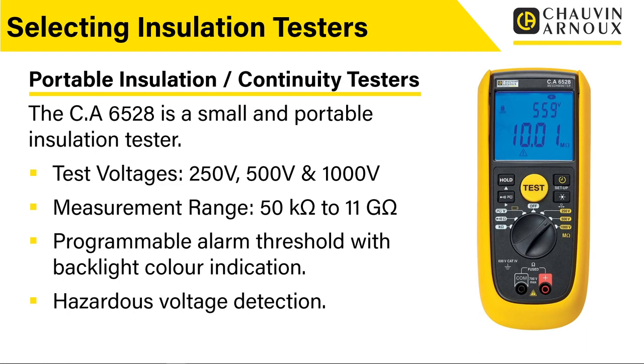So it's got a really wide measurement range there, and that means we've got a good range of values on this. It's got a programmable alarm threshold with backlight colour indication, so you can actually set at what resistance value you want the backlight to change red and tell you that it's failed or that it's lower than you would expect.